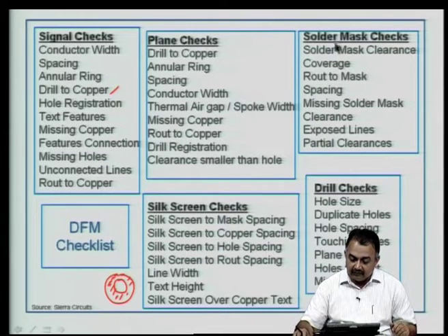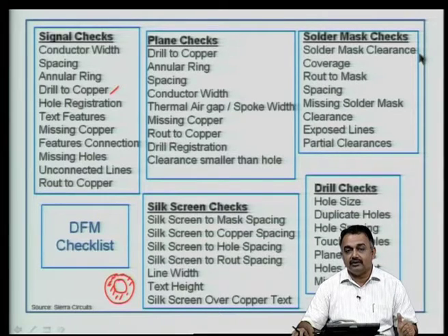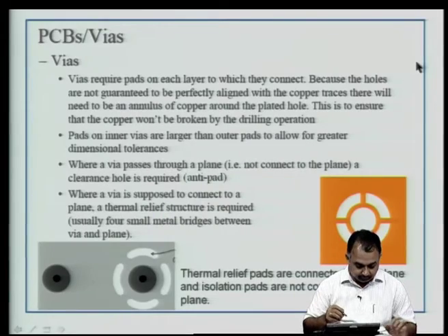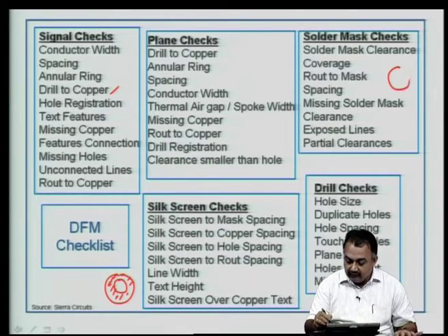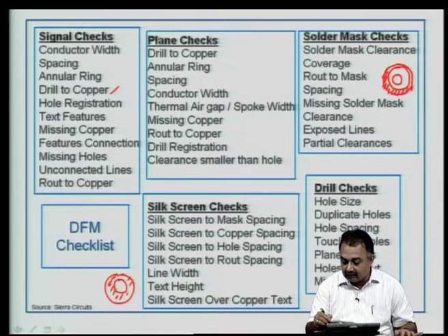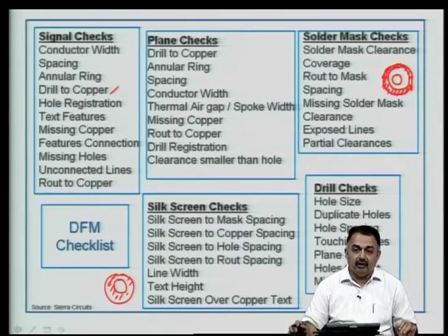When you use a solder mask, which is basically used to prevent bridging on the top side and bottom side of your final board, you have to look at what is known as a solder mask clearance. The solder mask clearance is usually about 5 mils. So, if you have a pad here, and this pad needs to be open, finally, this is the drill, you will have a third line, a third area which we call a solder mask clearance, which means the solder mask will not cover the copper area.